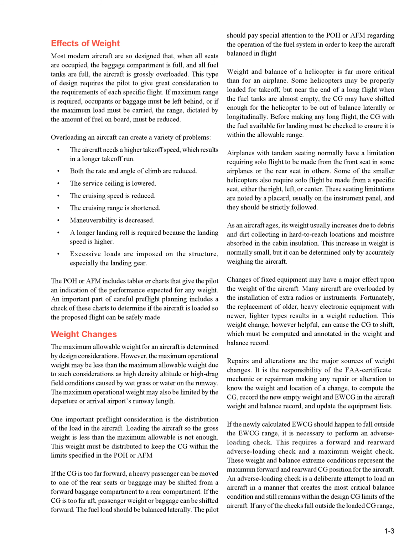The fuel load should be balanced laterally. The pilot should pay special attention to the POH or AFM regarding the operation of the fuel system in order to keep the aircraft balanced.